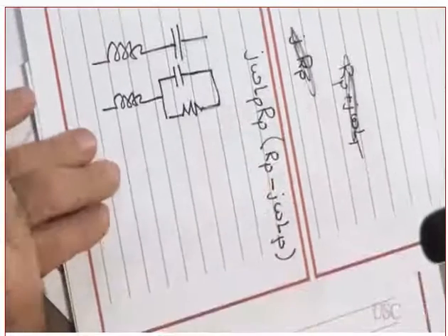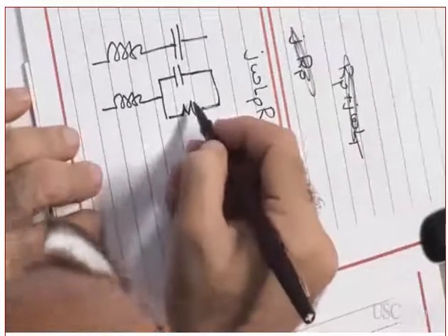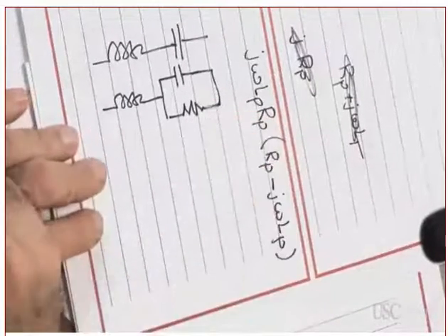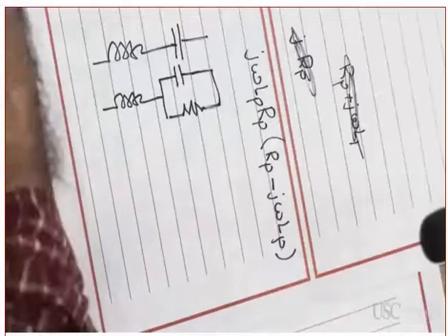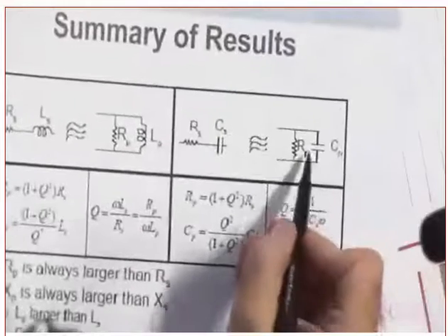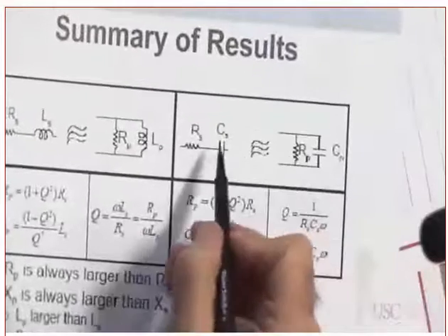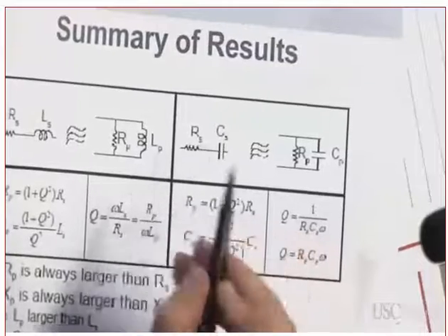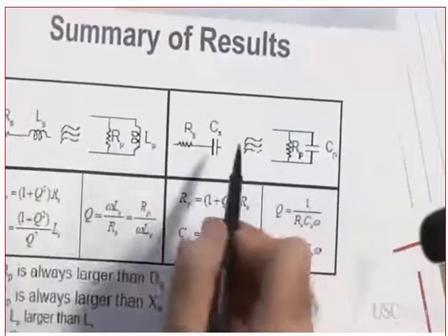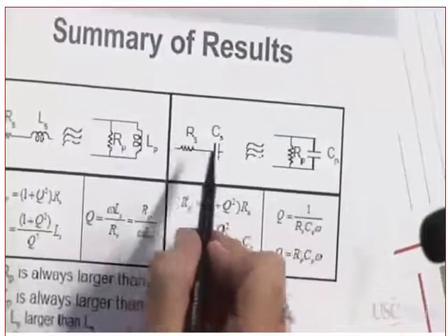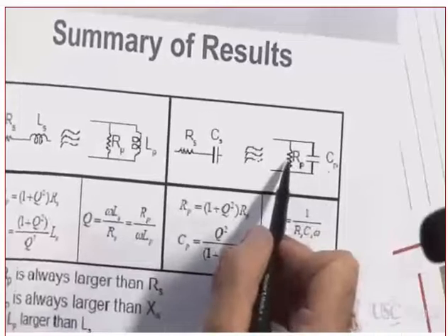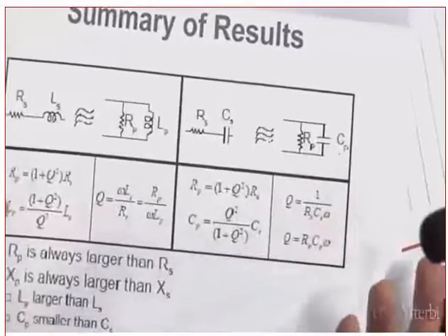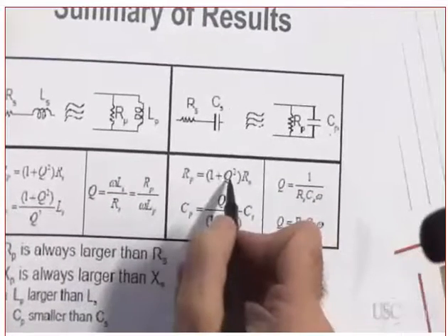Did you get this? But can I change the parallel now into series? Into series, which means I do the following. This, which is the parallel, I change it to the series. What is the unknown in this case? The unknown is the RS and the CS instead of the CP and the RP. Is it the same procedure? It's the same procedure. Yes?